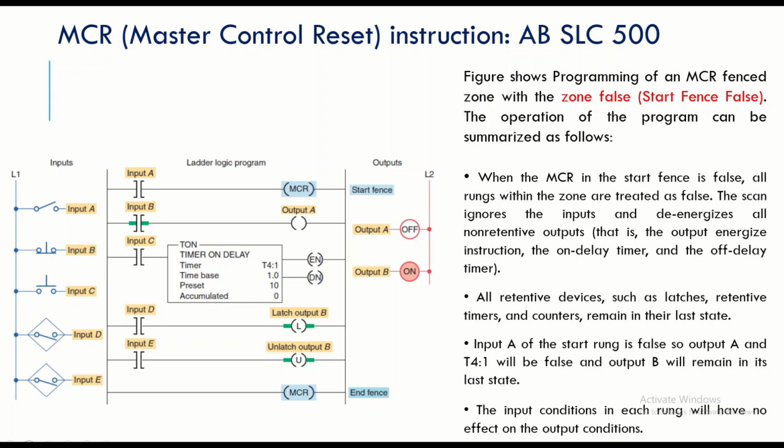But again, I would like to warn you that this master control reset instruction can never be a substitute for the MCR, master control relay, which is a hardware component.